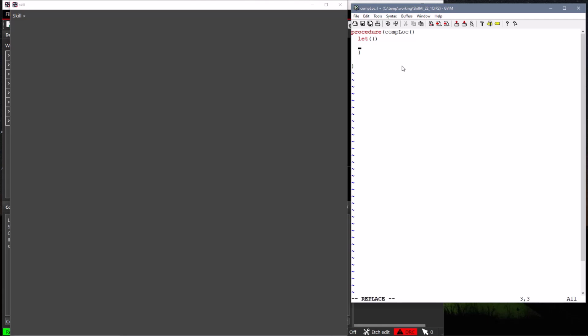There are multiple ways to get the DBID of all the components in a design, but the most convenient for this example is to start from the design DBID. The axlDBGetDesign function accepts no arguments and returns the DBID of the design that is currently open in the PCB editor. So we'll use designDBID equals axlDBGetDesign to save the design DBID in the variable designDBID.